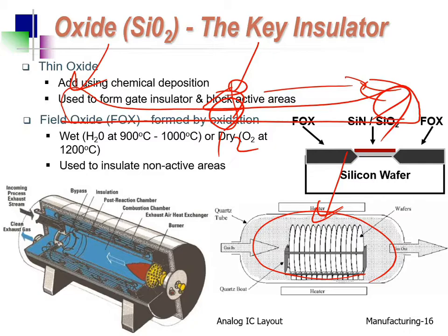If you have such a stupid layout, one here and two there, oh, sorry for that. You need to face a lot of systematic mismatch. Their performance will be really poor after fabrication. Okay? So, for systematic mismatch, usually for matching, we need to have a common centroid layout, just like what I say, 1, 2, 2, 1, 2, 1, 1, 2.